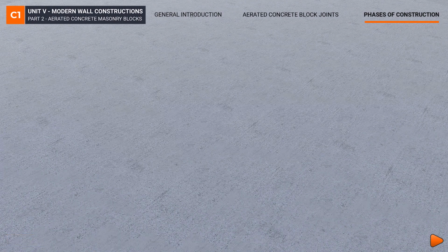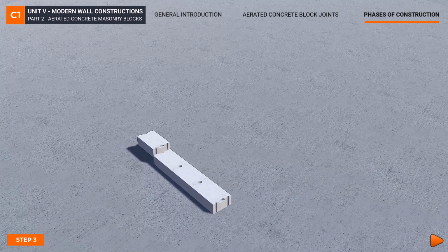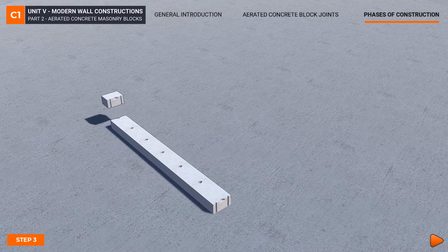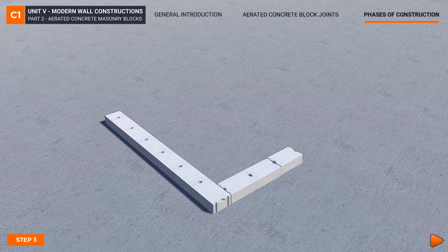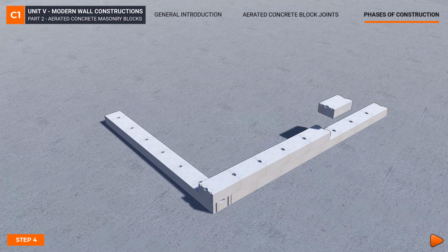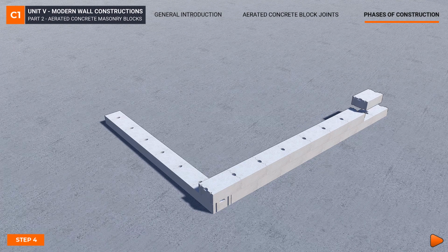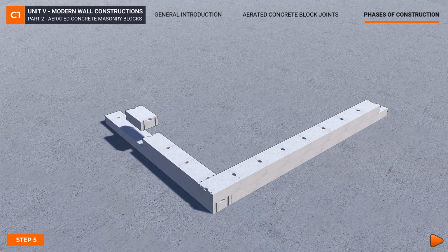3. Place the whole blocks of the corner, T-connection and wall end using a leveling tool, a leveling bar, 2 to 3 centimeters of mortar, a trowel and a rubber mallet for horizontal and vertical adjustment. 4. A masonry cord is stretched out between the already placed blocks, and the grid masonry is done here. The blocks will be laid along the original plan without vertical joints. 5. Check the levelness and sand the surface if there is more than 1 millimeter of unevenness.